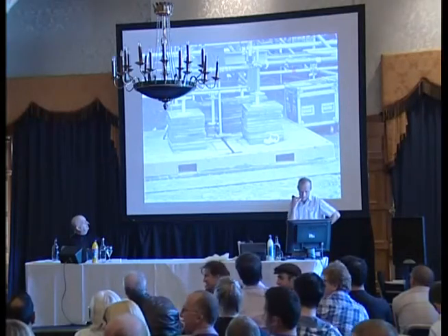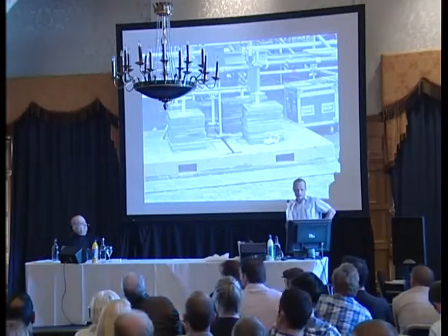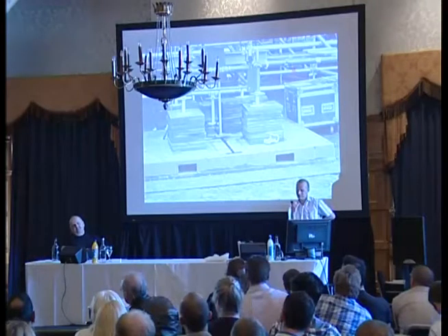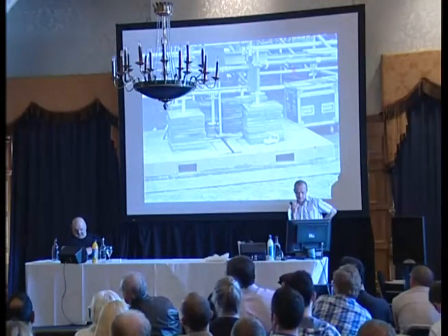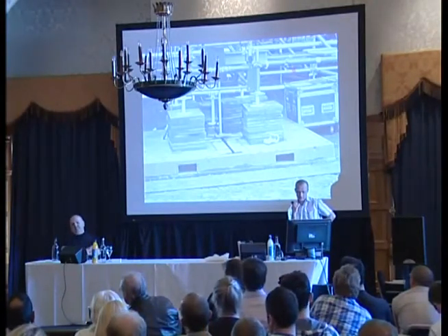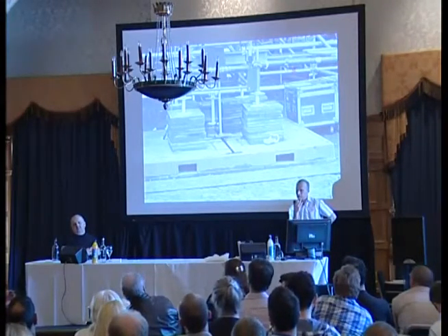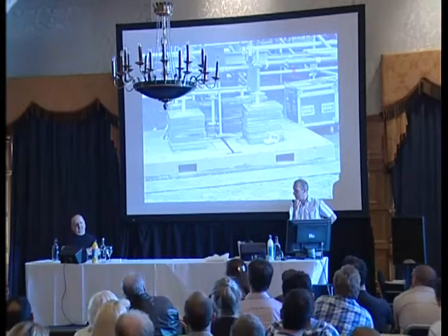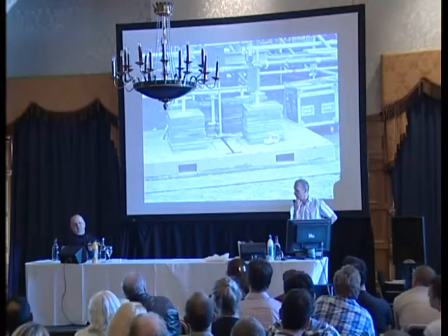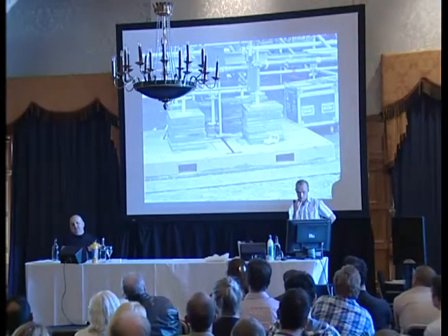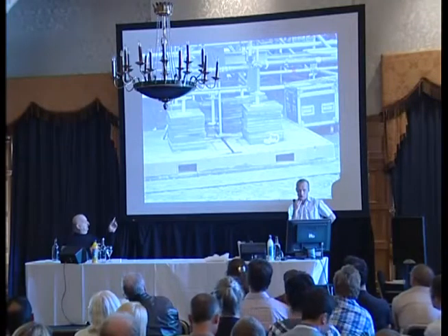You will not do that. I'm not saying go back and draw it, but the crew boss doesn't want to be in a position of saying that's right. What they would say is, I'm signing off that we've done this deviation, and I phone my office, and I've got evidence somewhere that my office said that's fine to do. What you can't do on the CAD is work out what the slip factor is between the plates if there was any lateral loading. And that's the issue I have with that.